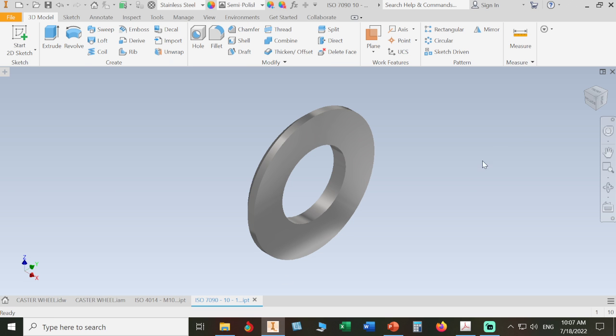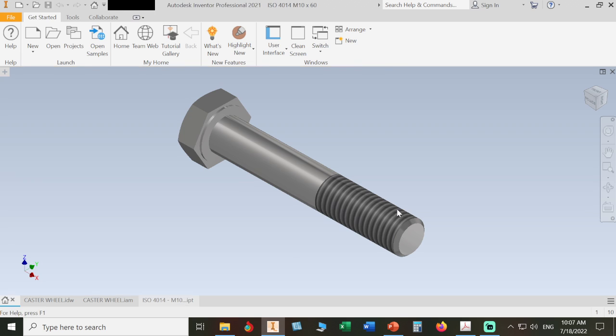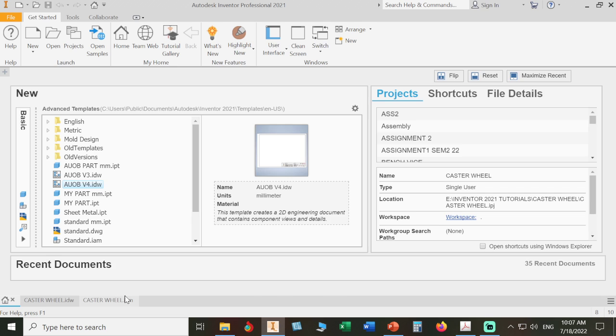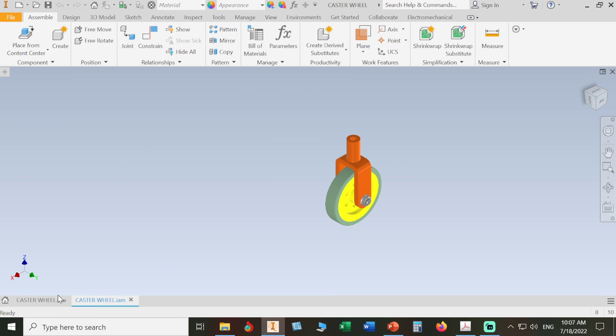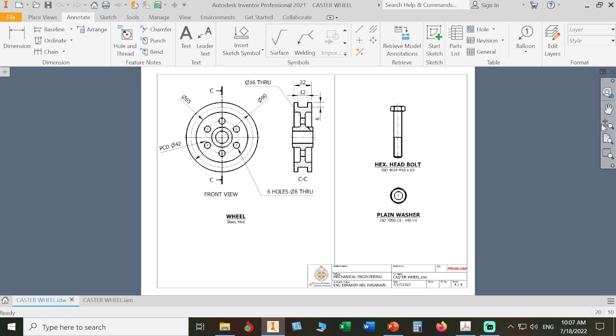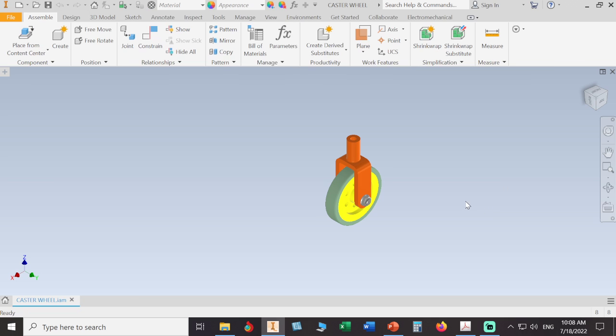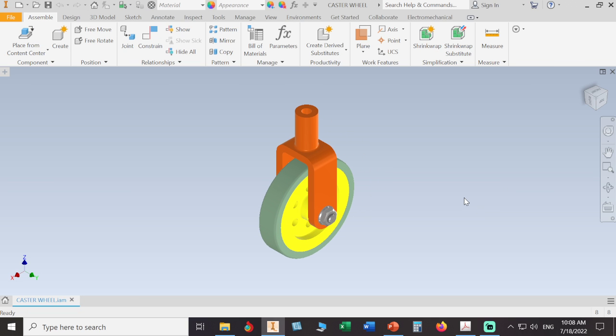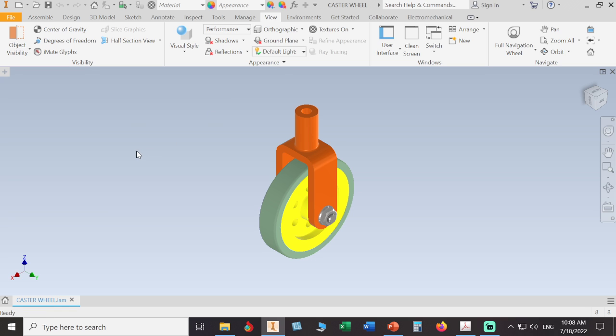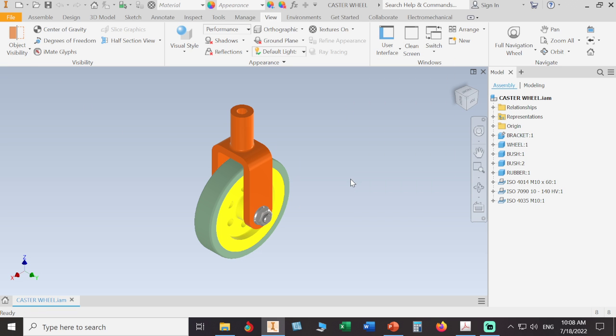Yep. So these, we don't need them. We'll close these parts. We just opened them to have them in our drawing. The drawing also, we finished with it. Save and close it. Then in order to pack your work, you have to be at the assembly environment. Let us bring back our browser from the model view, user interface and model browser. So you have to be at the assembly environment. What to do, then go to your file.